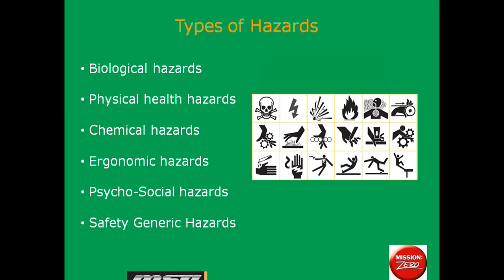What about the temperature? Then there's chemical hazards. Gases, vapors, dusts, solvents, smokes, fumes, and mists. What if a customer brings a sprayer into their dealership and the sprayer has chemicals in it? Well, how can we repair that sprayer if we don't know what chemicals are in it? We know that there's a chemical hazard. What if it's Lorsban or a chemical product or an insecticide that we are not aware of how to handle at our dealership? So be aware of chemical hazards.